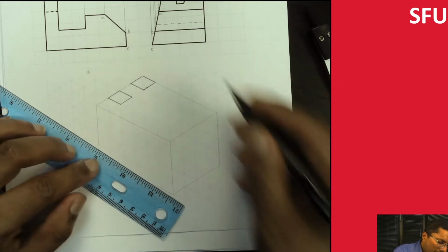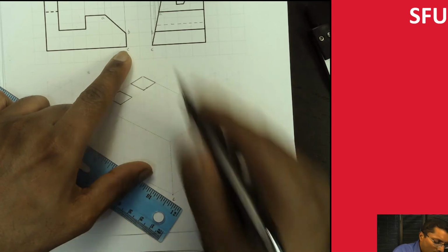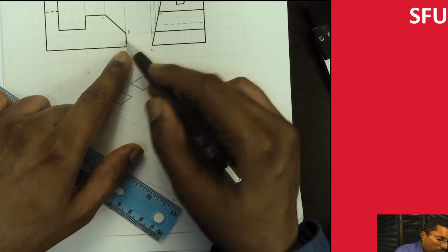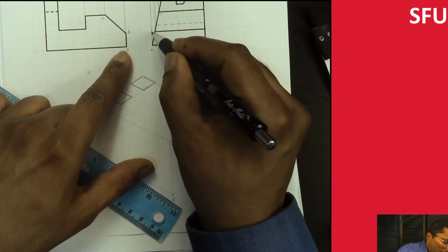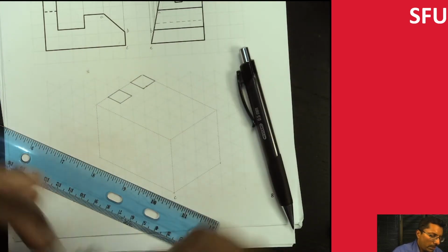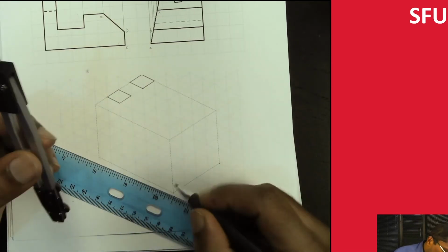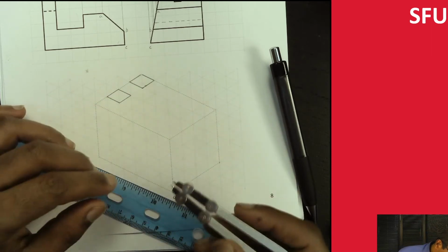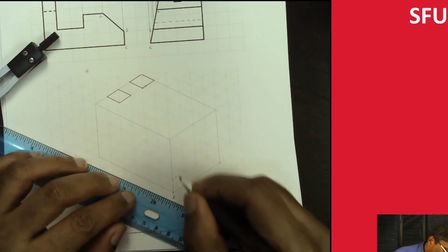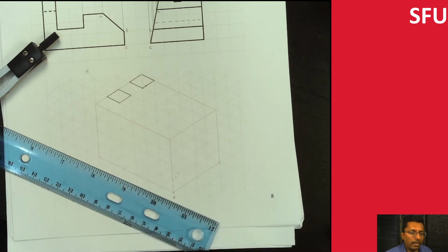So let's do this. The back point here is located exactly in this vertex over here. That's good. The bottom point C is also located on the plane, so we mark that. The point B, where is it? From this view, I know it's exactly located on the front plane, so it's going to be on this plane. But from this view, I know it's offset a little bit into the front plane. So I can again use my compass over here. I'm actually 1 centimeter. So here, here, and this is going to be my point B over here. We put a small b, really faintly because we don't know how much space we'd need.